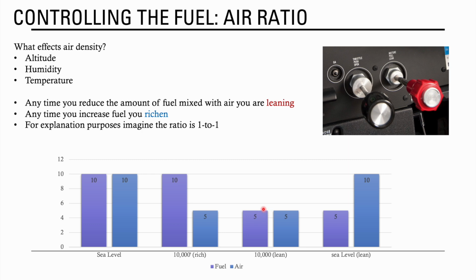Is it dangerous to run a rich engine? Yeah, so the reason why it would be dangerous is because if you have too much fuel going into the system, you can't burn all of it, and so you get buildup on the spark plugs. And eventually, if there's enough buildup on the spark plugs, they can't fire, and so they would just fail. So if you have one cylinder that's not producing any spark or combustion, suddenly you get down to 3 cylinders, you have a lot less horsepower, and it's pretty common that if one spark plug has failed or one cylinder has failed, the rest are going to follow suit because the same condition has occurred in all of them.